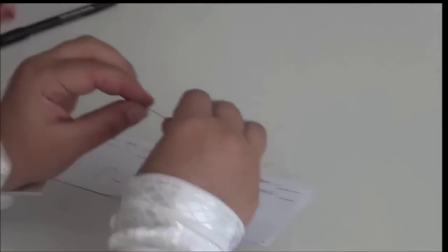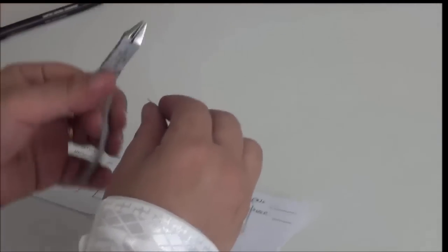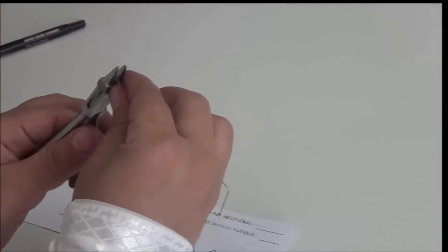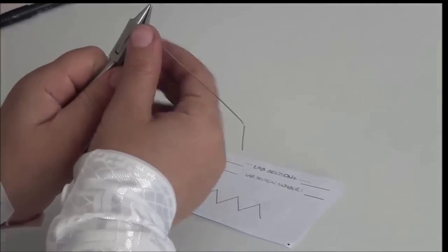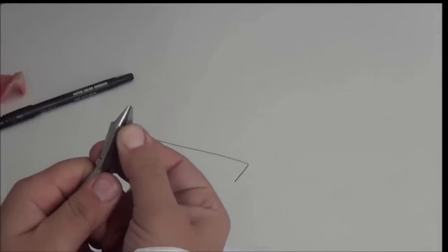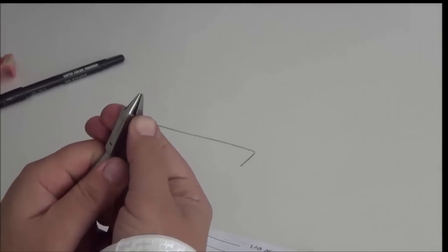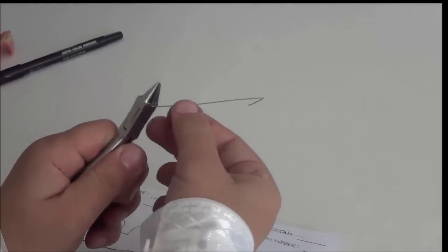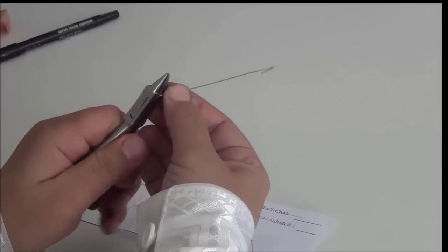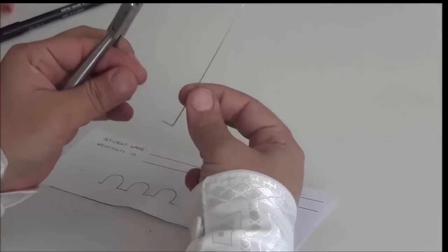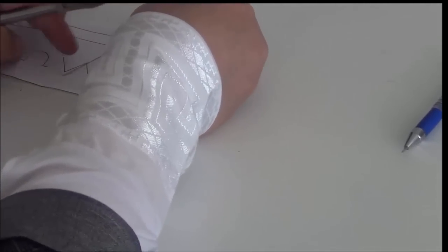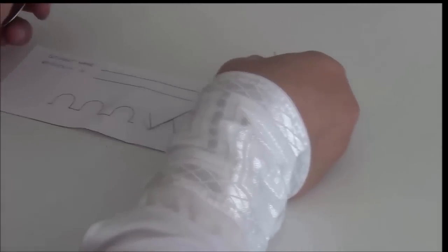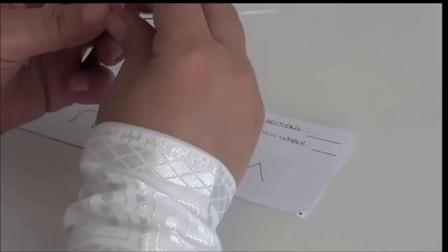Basically, angles are easier. When we locate the angle that we want, we simply press against the straight part of the pliers, and we will immediately get a 90 degrees in this direction. But suppose I want less than 90 degrees. This angle that we're following is less than 90 degrees. How do I get less than 90 degrees?